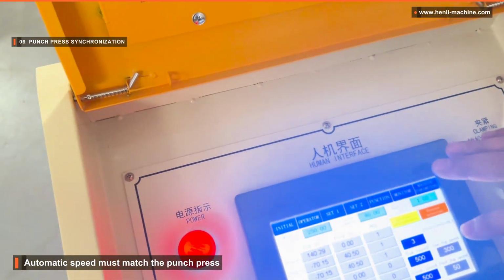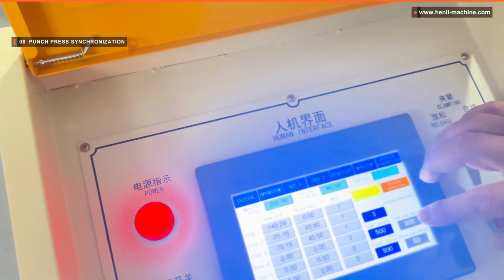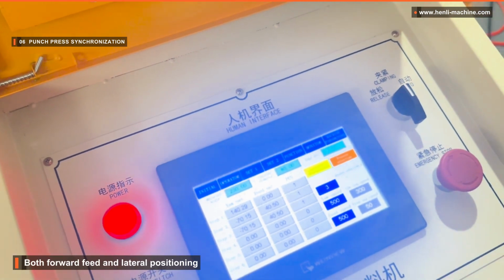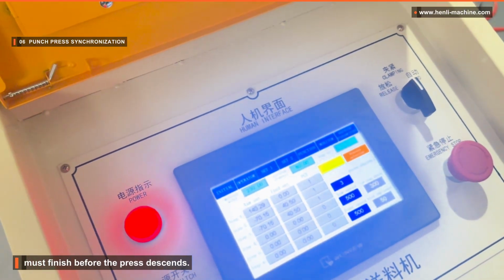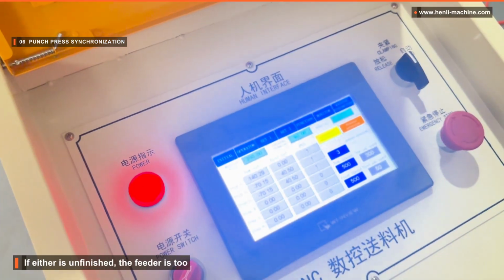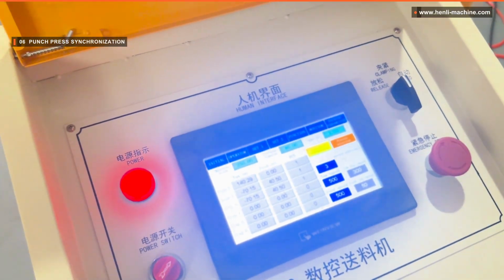Automatic speed must match the punch press cycle. Both forward feed and lateral positioning must finish before the press descends. If either is unfinished, the feeder is too slow or the timing is incorrect.